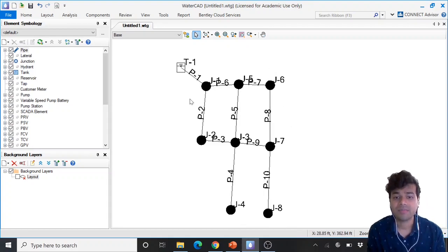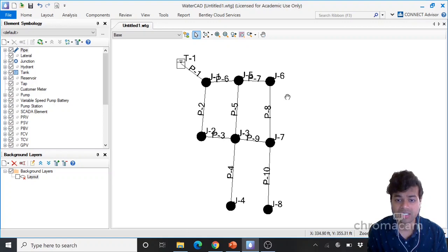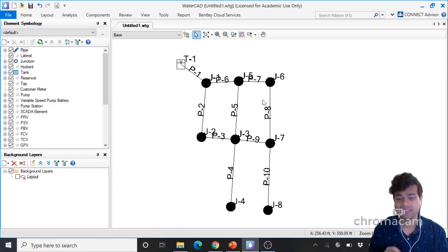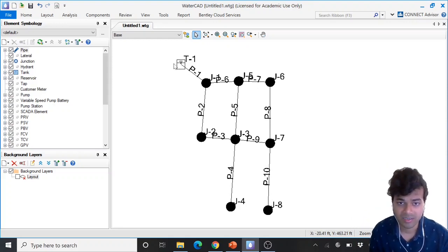Okay, it doesn't matter from where you start and where you end, but if you want to match your result with me, then you can simply follow my sign convention, right? Like pipe 1, pipe 2, pipe 3, pipe 4, and then from junction 3 to junction 5, pipe 5, 6, 7, 8, 9, and 10. Okay, how many junctions are there? 8. Okay, so this is our layout.